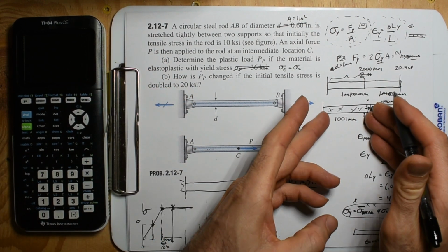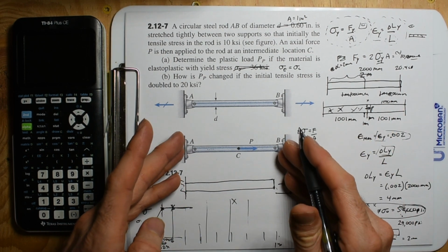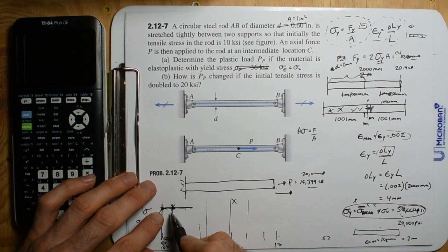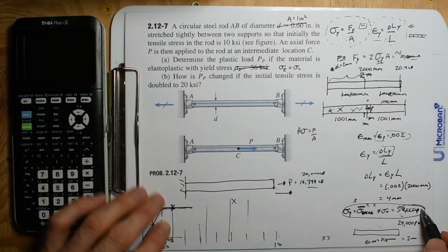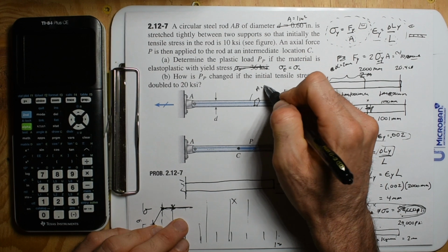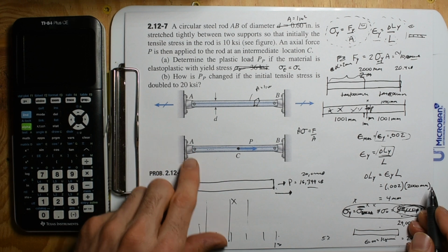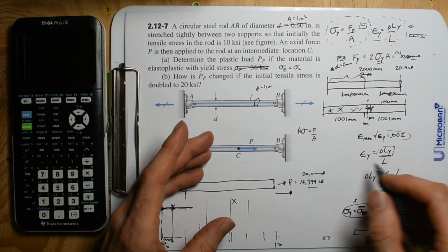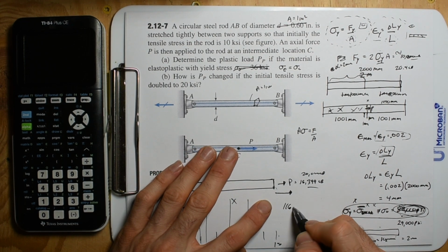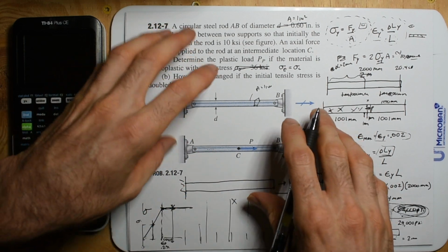And so you have designed something that reached its plastic limit. It reached its ceiling, but it's still a very functional piece that's still holding, in this case, 58,000 pounds. Because now I'm going to say that this is a 1 inch square bar. Area is 1 inch squared. Cool. So that side of the bar can carry 58,000. And just know that this problem is just double that. What's the max load P force you can put on it? Well, it's just double 58,000. It's 116,000.